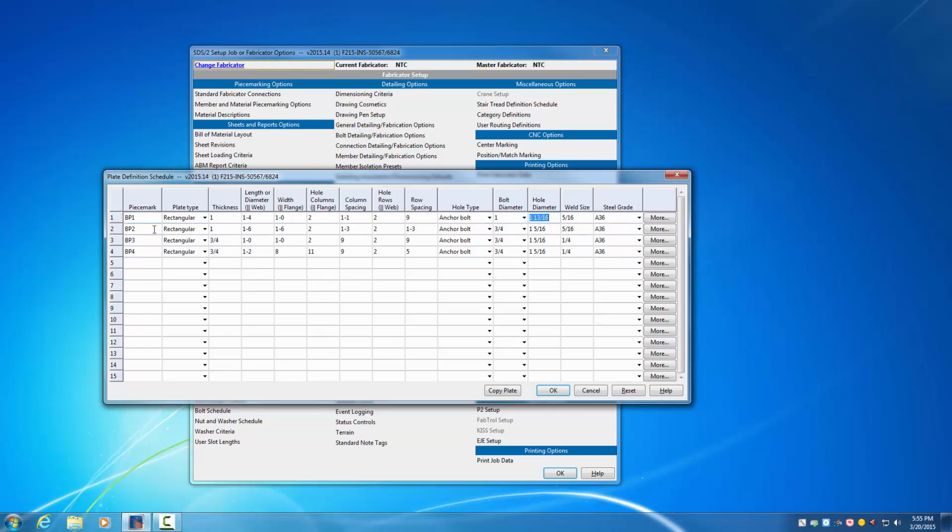So the next base plate, if you stay on grid line A, intersection A and 3, if we call that base plate number 1 also, because it is the exact same plate as the previous one. It's a 1-inch thick plate, 12 by 16. Same, it has to have the same size anchor bolts.